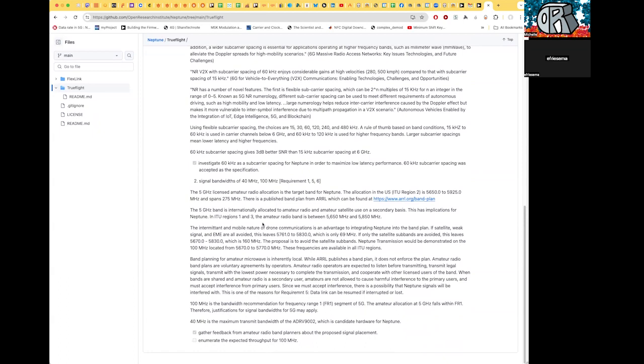So yeah, these are all good. Obviously, if you have 100 megahertz to hide in as opposed to 40, there are a lot more things you can dodge, like Doppler shifts and other things that might force you to spread out. If you have 100 megahertz, that gives you a bigger velocity range you can cover. It gives you a lot of places to hide. So if you have some specification that works at 40, it should work at 100 if you have the hardware. It's definitely something we'd like, but we can do 40 now. It's like the old general patent thing: a good plan now is better than a perfect plan two weeks from now.